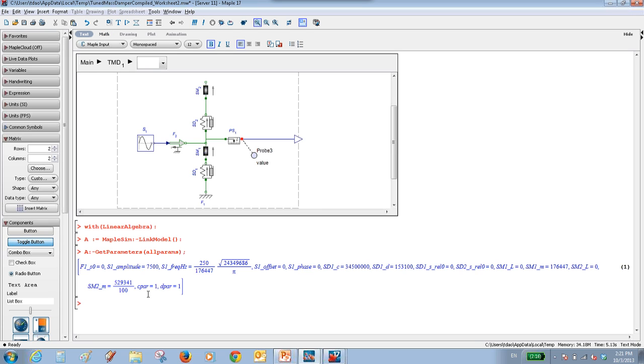What I want to do next is generate C code for this MapleSim model. This C code will allow me to execute the model simulation faster, since it has been optimized. The reason we need the C code is that optimization processes usually require us to run the simulation hundreds or even thousands of times, so having optimized C code with a short execution time will help a lot with the optimization process.